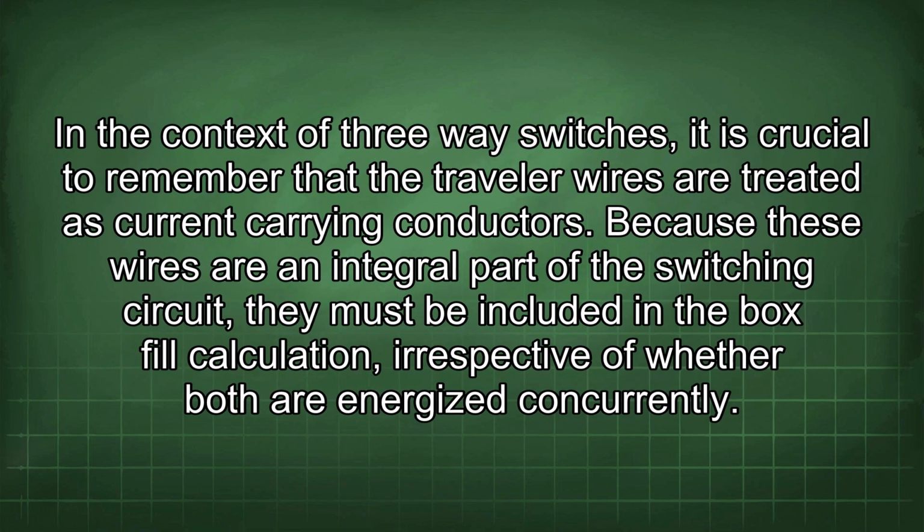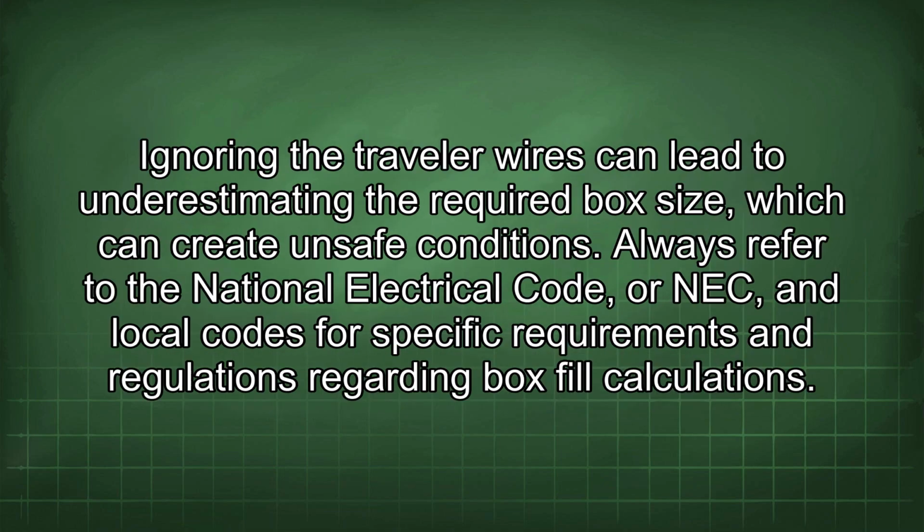In the context of three-way switches, it is crucial to remember that the traveler wires are treated as current carrying conductors. Because these wires are an integral part of the switching circuit, they must be included in the box fill calculation, irrespective of whether both are energized concurrently. Ignoring the traveler wires can lead to underestimating the required box size, which can create unsafe conditions.